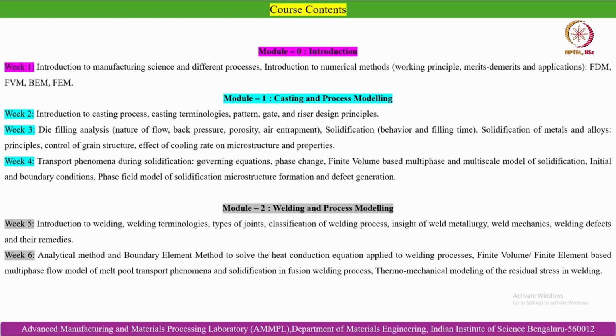And then followed by that we will be discussing transport phenomena, which is one of the most important and critical parts of the casting solidification processes, because it is the melt flow which governs whether there will be any turbulence caused within the cavity, whether there will be any bubble damage or bubble entrapment or analogous blowhole formation and so on so forth. So we will be studying the transport phenomena of the solidifying melt. We will discuss governing equations, phase change process, and also finite volume based multiphase multiscale model of solidification.